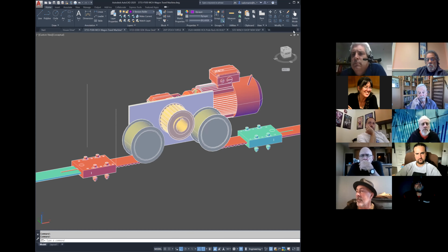But before we get to that, you can imagine this same system here. You could adapt this not just to timing belts, but you could use roller chain as well. But it tends to be a bit noisy, and plus it's way more expensive than cable. You want to move a platform 40 feet, you've got to have 80 feet plus of roller chain. And there's no way to make them quiet really, because the nature of a sprocket meeting a roller creates noise. But it is a way to make it work.